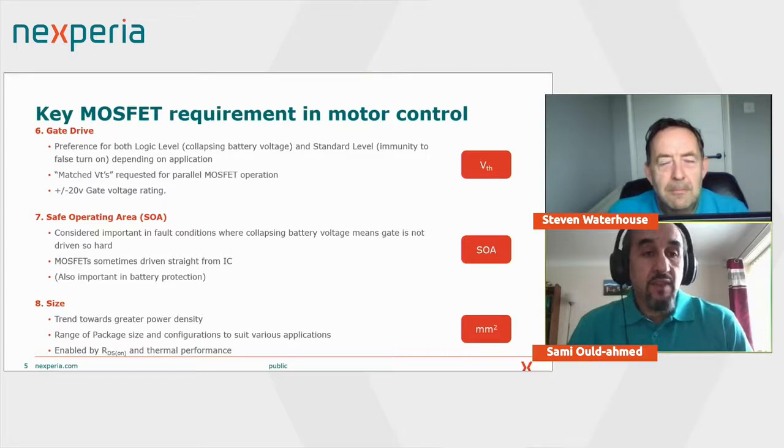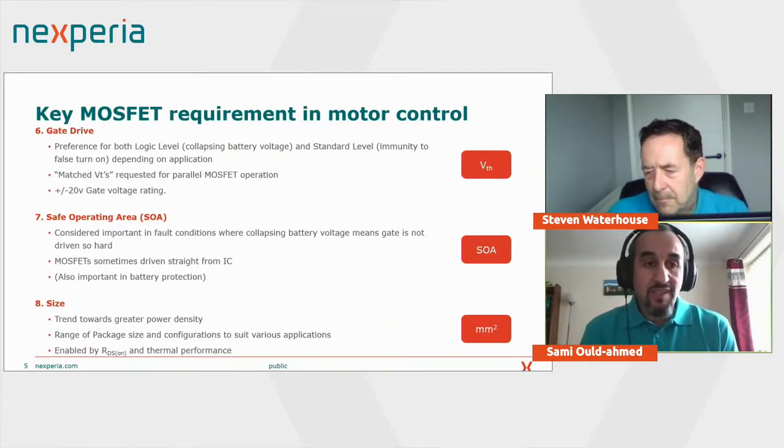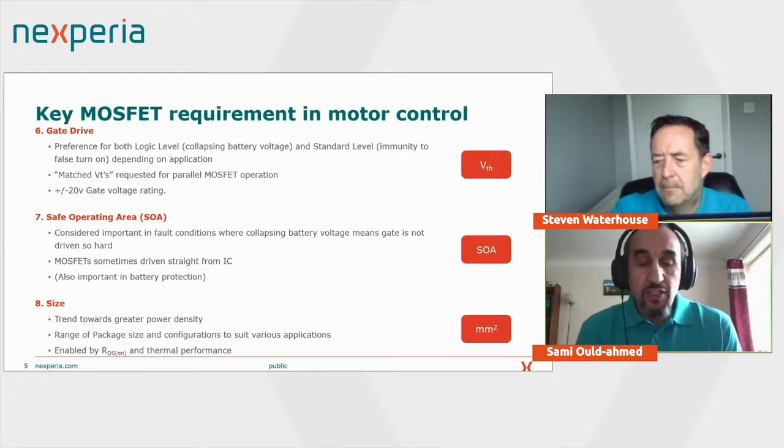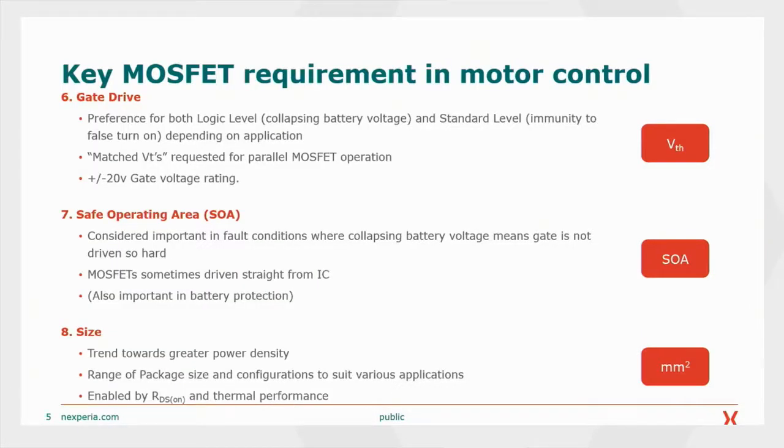The safe operating area. The technology provided in our MOSFETs gives one of the strongest SOA in the devices. This is important in situations where it is sometimes not thought of. If the MOSFET is switching off while trying to control the high current going into the circuit, it is put into linear mode, and therefore the SOA is most important for that application.